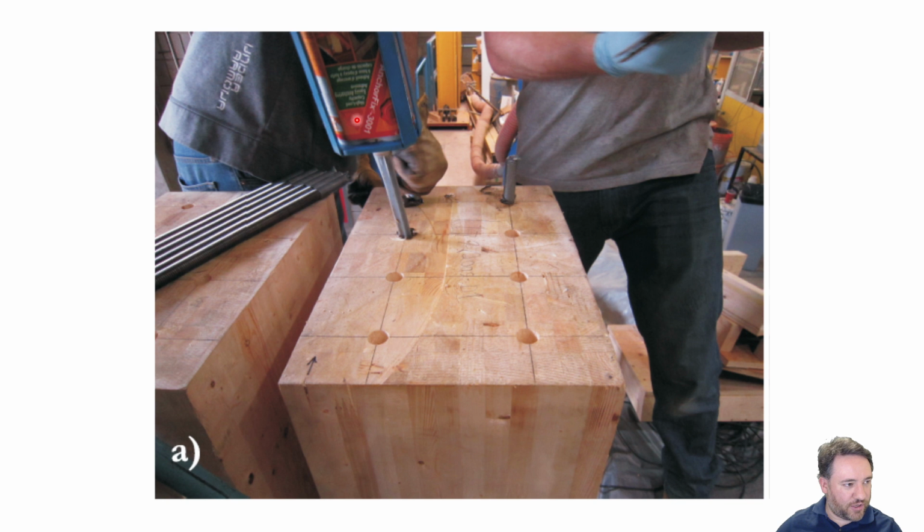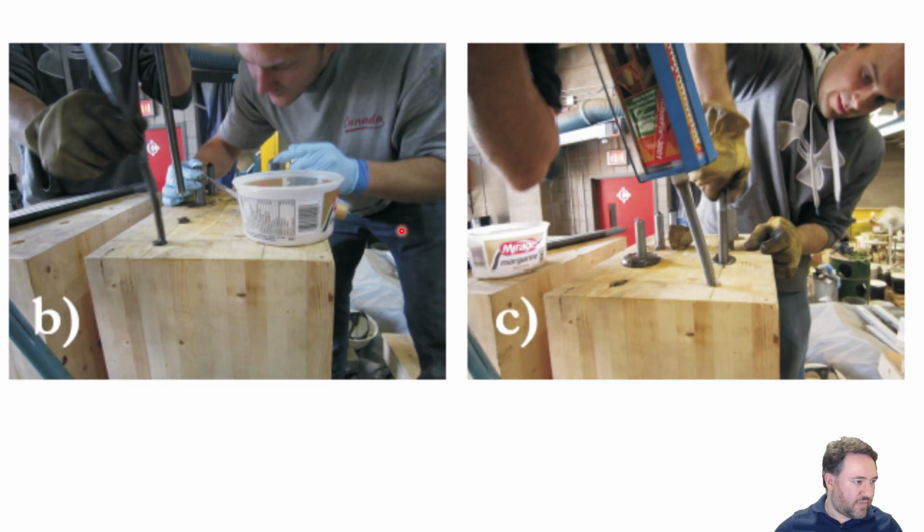And this is a two-part epoxy. So basically it comes in two different containers, and you put them into what's effectively a big caulking gun. And then in the nozzle here, the two chemicals mix. And when they mix, that's when they'll start to set. So we mix the two-part epoxy, we inject it into the holes, and we install the rods. You can see the remainder comes out the top.